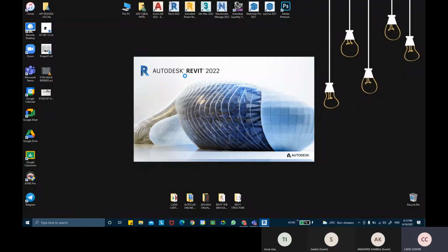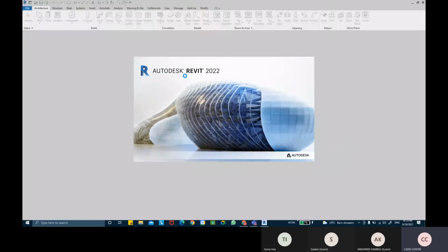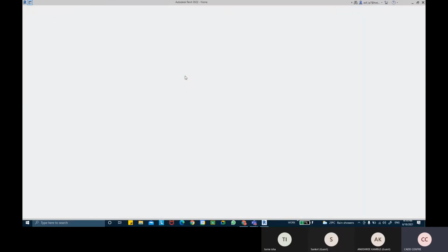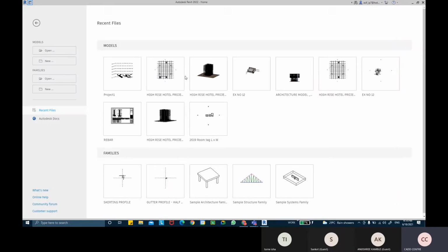So in yesterday's class, we did the staircase editing. We did the landing type edit and the support editings as well, the middle support and the side supports. In that, we saw how we can add two different profiles to the supports. Then we saw the carriage and the stringer options that are available in the supports here.